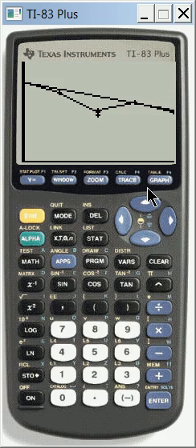Now here you have essentially the energy grade line, and here you have the ground grade line. The difference between this and this is actually P over gamma plus the velocity head. Realistically, you need one other line typically, and it's the hydraulic grade line, one below the energy grade line. We'll play around with these and change the velocity in the next video, but that's how you go about doing the program, and the program should be updated with an 1102 revision date.